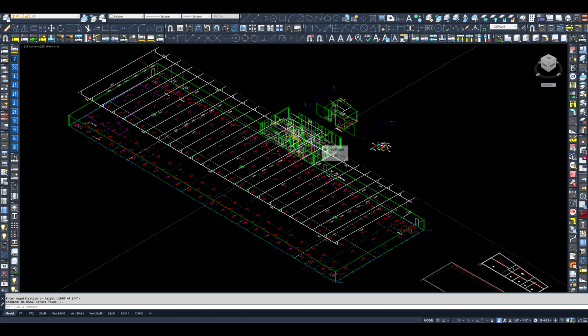This error happened on a 3-story, very involved project, and I was furious thinking I had lost my progress, but that was all it took. Much more complicated system than this, but it fixed everything simply by changing that from fixed to not in the permanent properties. So if you're having that issue, I hope that helps.